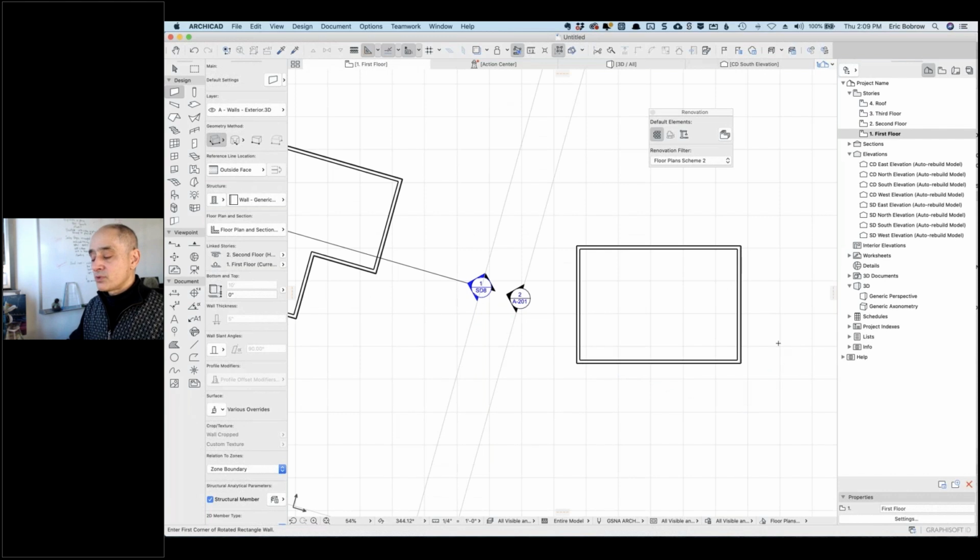So now, temporarily, this is oriented this way. And of course, I can work here. If I'm drawing a wall, let's just do single wall, it's going to snap to that and the 45s of this particular angle. And if I were to type in something like X, you can see that X is whatever I was drawing and Y is 0. So it's rotated the axes to make it simple to draw and define things.